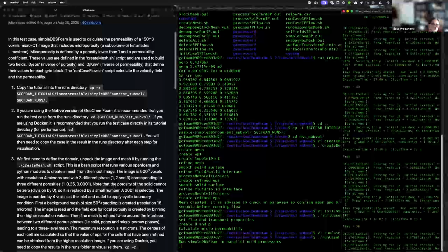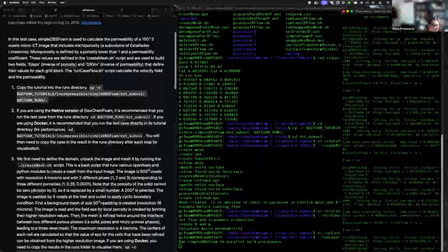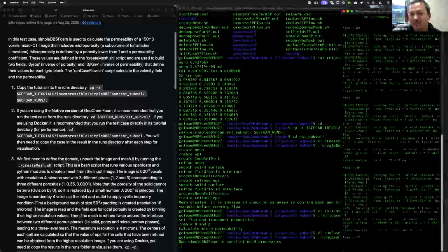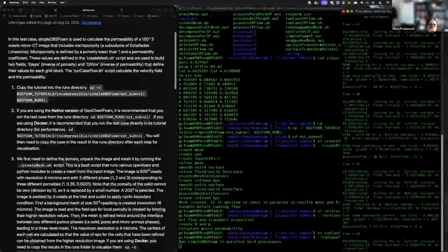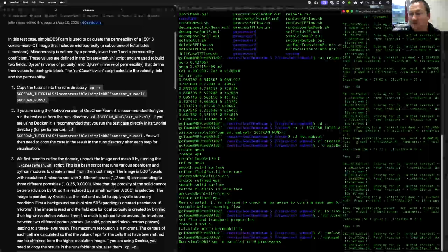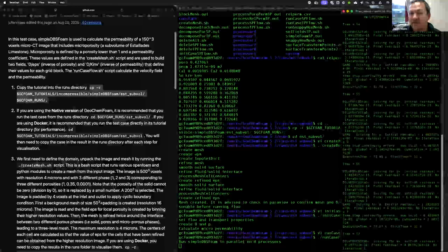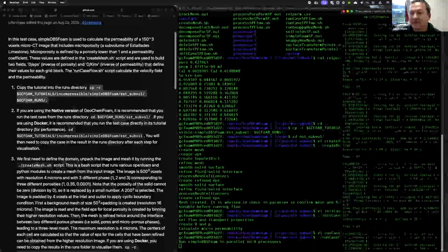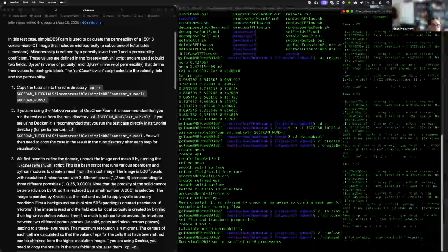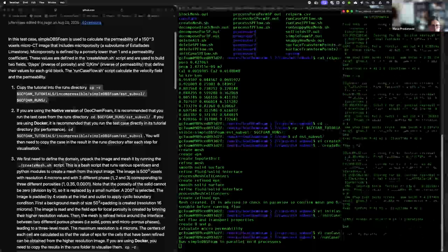And it's struggling with the sharp transitions, as long as you smooth the transition. Yeah. Brinkman is struggling with this because of the division by zero, so we have to put in a tiny bit of permeability, which means the pressure and the velocity will go to zero inside the solid, but the pressure is nonsense. And that could create some problems when it's sharp.